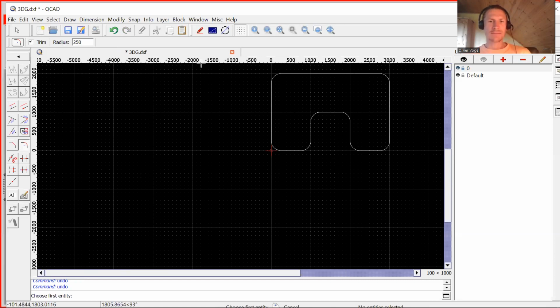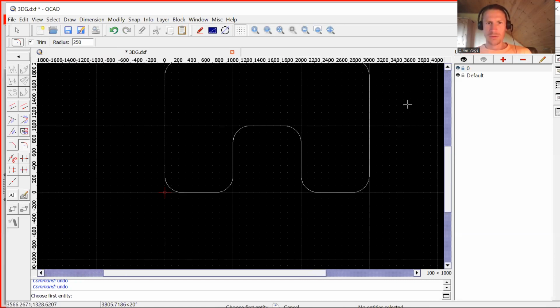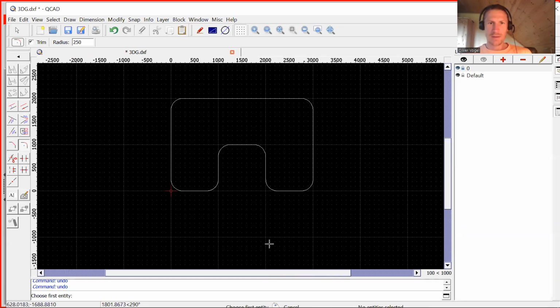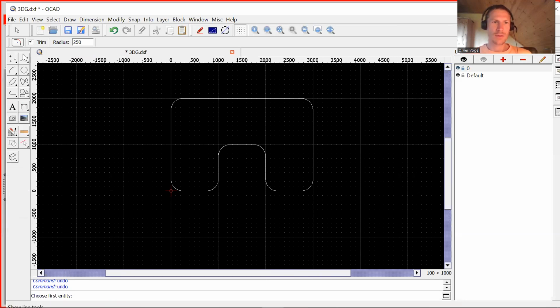So last but not least, you notice that we have now more segments, but we need to have a polyline that TrunCAD can work with. That's why we go here one step back, and we are using here the polyline tool, what you see on the left side. And here we activate create from segments.